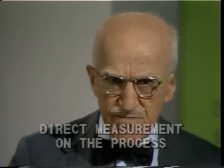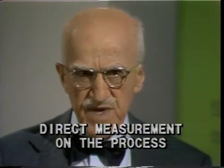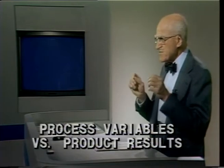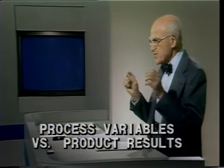Second, we can assure process adequacy by direct measurement on the process. An example is the sterilization process used in pharmaceutical manufacture. We can use thermocouples to check the heat distribution of the sterilization chamber. That tells us whether all areas of the chamber can attain the minimum temperature needed to destroy dangerous organisms. The third approach is to discover the relationships of process variables to product results. Knowledge of these relationships is the key to high process yields and to improvements for the future.